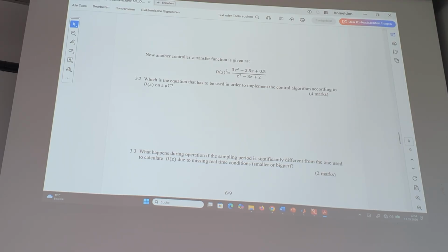So people sometimes tend to think, oh, if I calculate the equation much faster than the 1 second, everything is even better. That's completely wrong. If you define the sample time to be 1 second, and you calculate your equation faster, maybe in 100 milliseconds, then you have to wait another 900 milliseconds until you're allowed to calculate it the next time. That's very important, not to think, oh, I'm even faster, so it's better.